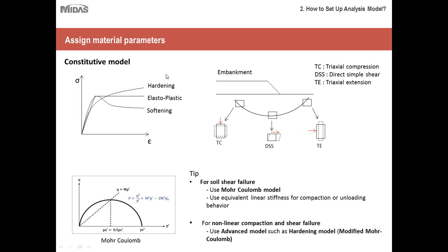So now based on what type of stresses they are subjected to, different curves are responsible for that behavior. So it is very important that you select the correct constitutive material model that correlates the stress strain graph with the stress paths that happen in the soil strata. And for this, the most commonly used constitutive material model is Mohr-Coulomb.